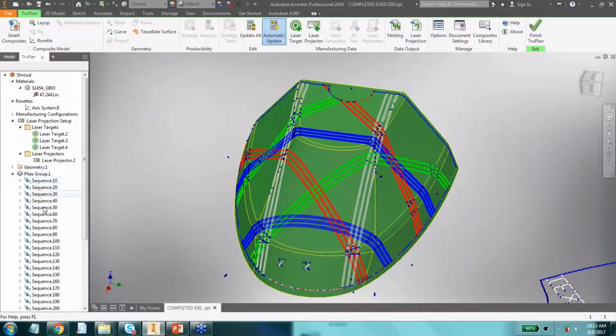So we've got the definition for each ply in addition to the overall contour. And that definition includes things like material, direction, and so on. It allows you to bring the kind of information directly over from CATIA without having to redefine that. So everything you saw in your stacking tree now exists here.